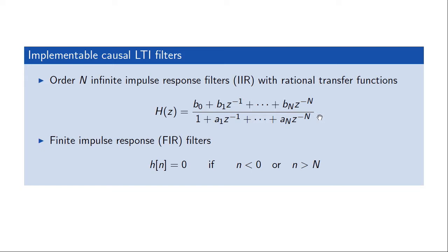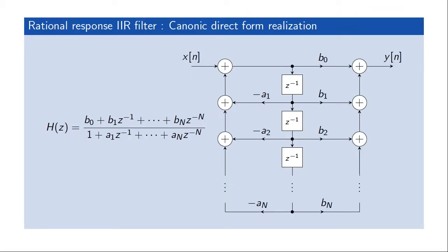So this set of filters would also include these FIR filters that we looked at before when doing the filtering with FFT in the frequency domain. But in the general case, since these filters will have an infinite impulse response, you couldn't implement them by simply convolving the impulse response with the input, but you could implement them in this recursive structure that I'm sure you've seen before.